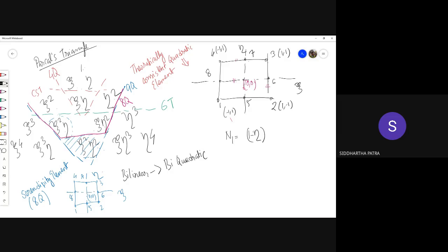So I'll be considering this line, so that on this line shape function 1 is 0. Now this line xi equals 1 is also 0. But then I'll not be considering either the 8 6 line or the 7 5 line. I'll simply be joining 8 and 5, because I only have the freedom to incorporate 3 linear equations, because I am going up to cubic term.